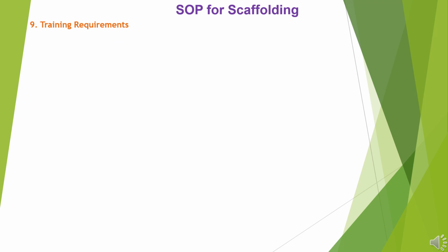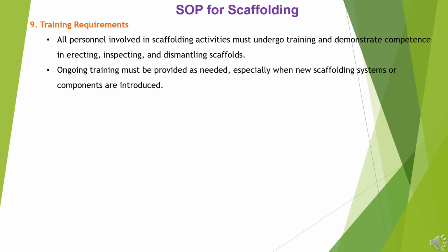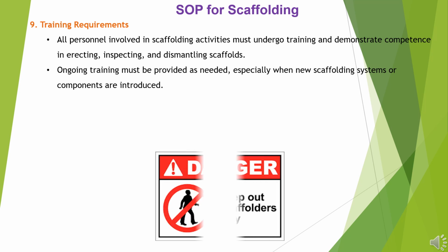9. Training requirements. All personnel involved in scaffolding activities must undergo training and demonstrate competence in erecting, inspecting, and dismantling scaffolds. Ongoing training must be provided as needed, especially when new scaffolding systems or components are introduced.